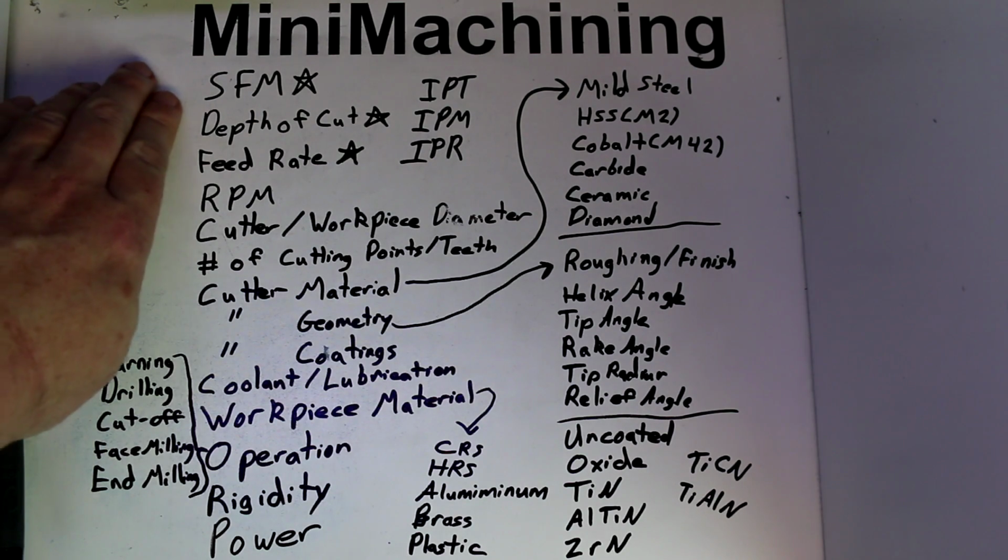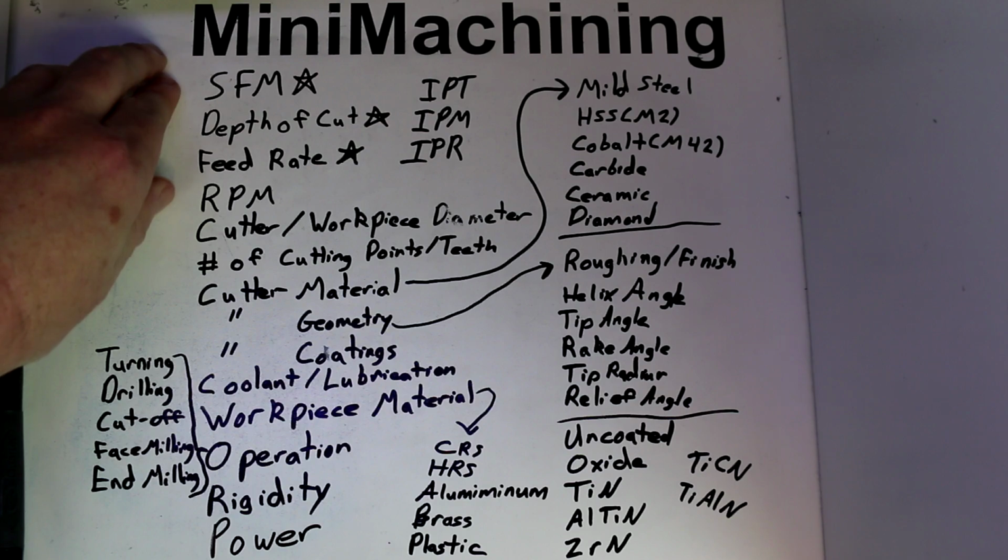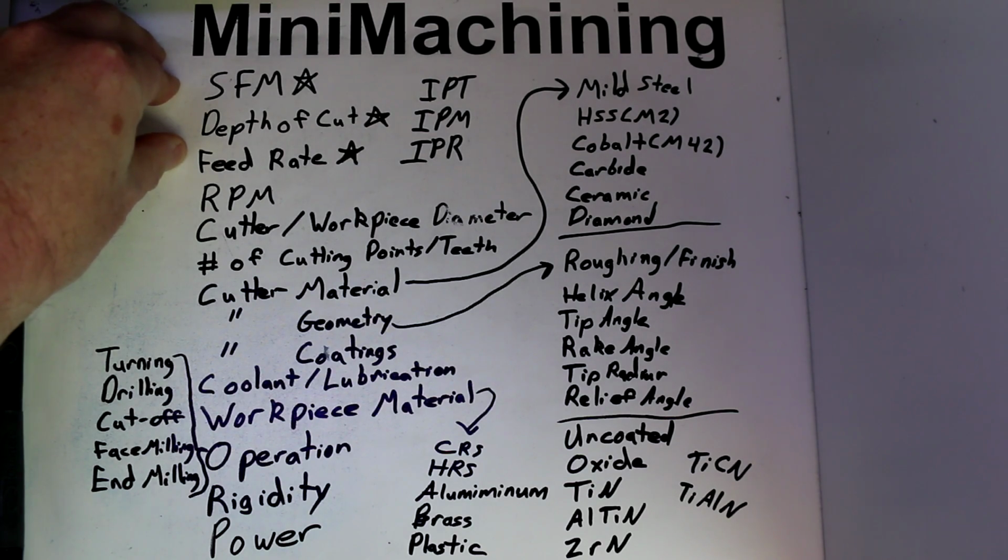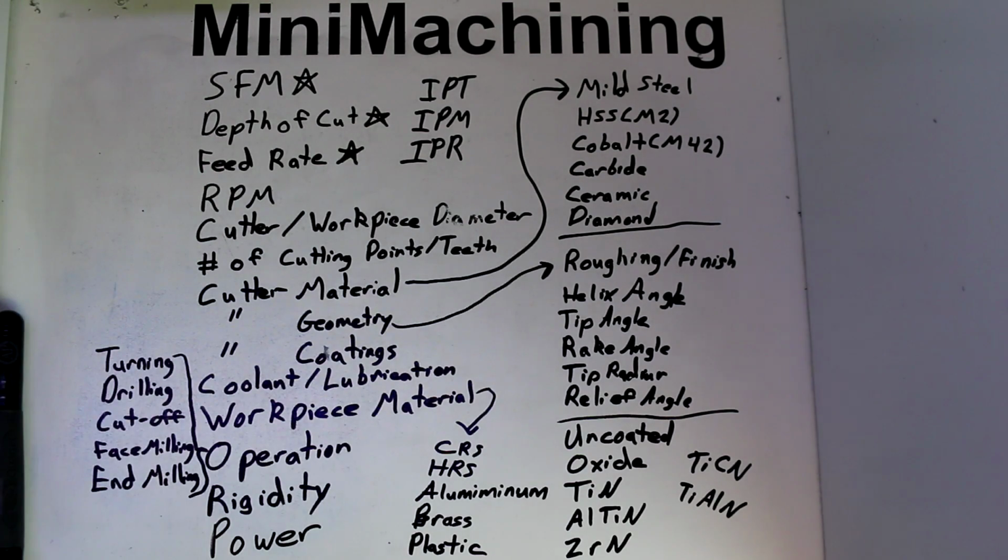So we can use the machine to spin at a very specific RPM with a very specific feed rate and see how that affects how long it takes to make a pass on a particular part, what type of vibration we get, and how it affects our surface finish, as well as both our workpiece and possibly our tooling temperatures, which will give us an indication of our tool life.